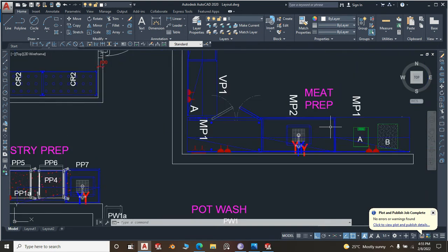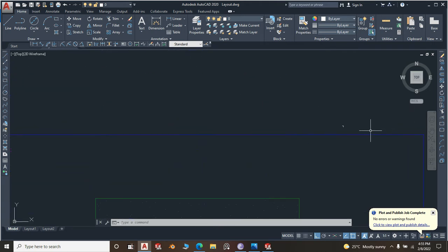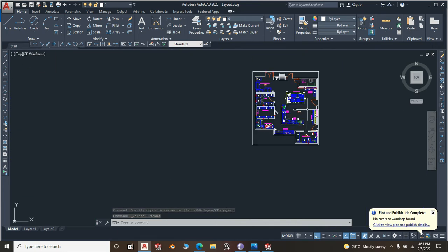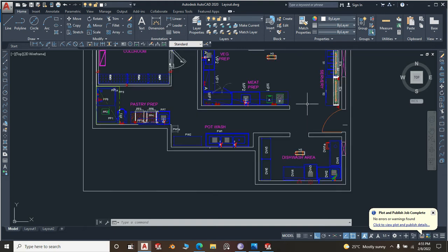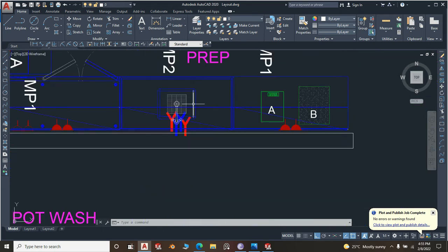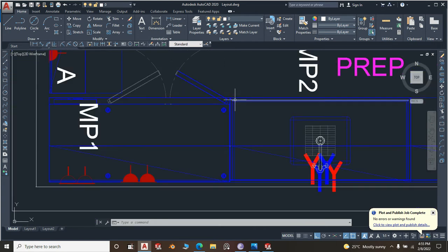So when you're designing your fabrication, you first check the imported items, what series are there in the market. If whatever size you're looking for has a series of 600, then it is important to design your fabricated items with a depth of 600, because you don't want there to be edges protruding.